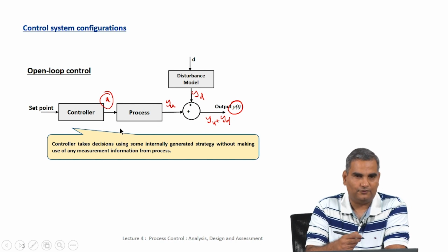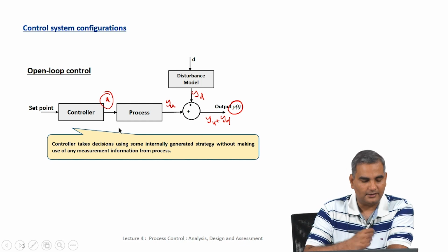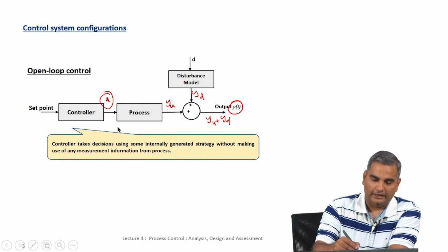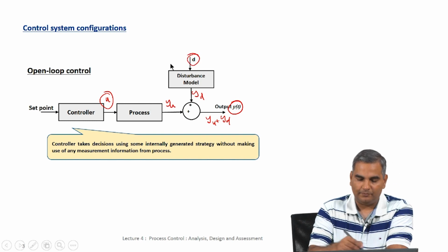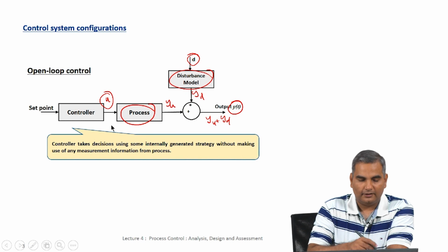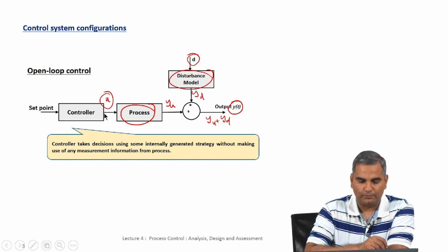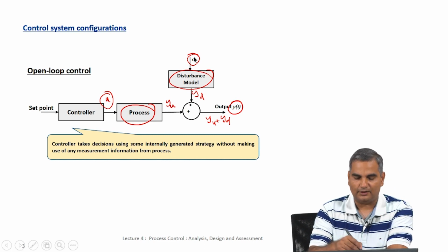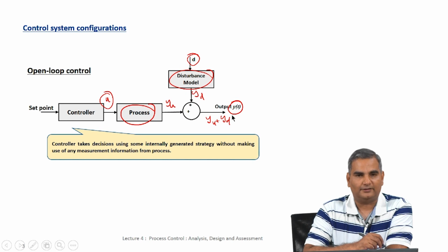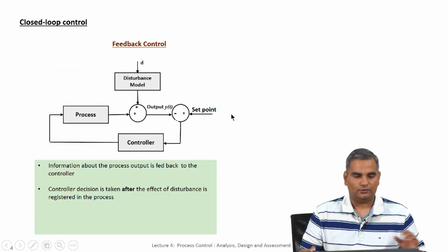And as we discussed before, this open loop controller is unlikely to work very well, simply because the models are not perfect. If you have perfect models, if you know the disturbance exactly and you have a perfect disturbance model and a perfect process model, then it is possible that we can just do this control in open loop, where we simply say what should the u value be given the exact disturbance value and exact models, so that Y takes its set point value. But this is unrealistic in real life situations.